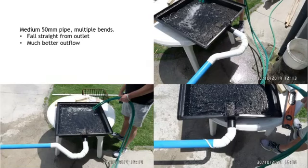That's with one bend. Here's another little configuration. Medium pipe, in other words, the medium length of pipe. It's a little bit longer than the first couple. There's still 50 millimeter pipe. There's multiple bends. In this case, they're all 45s, and you can see there's two different configurations there. The fall, though, I made sure that right from the get-go, from the outlet, even the bends, that configuration, it's all got a fall, and it's all sloping towards the outlet.